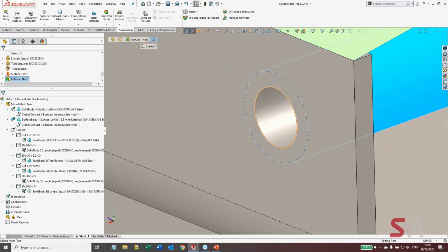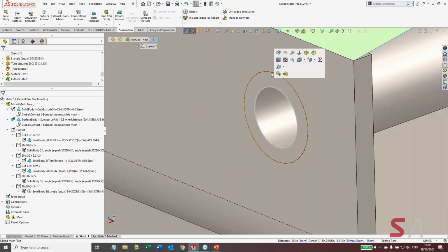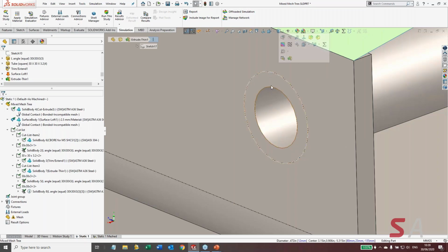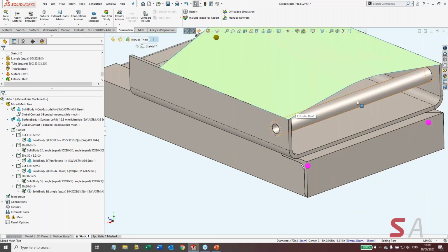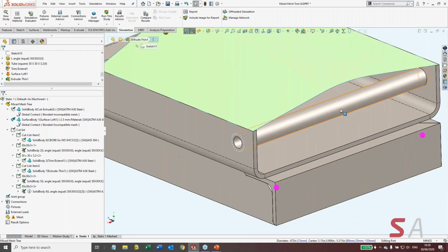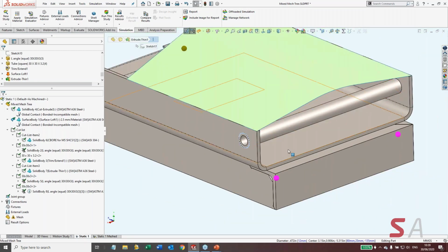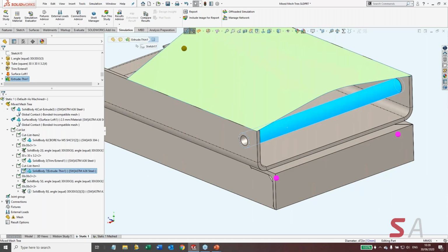So what's my radius here? My outer diameter is 12 millimeters, and my inner diameter is 8 millimeters. So I've got 2 millimeters of thickness. So we're talking about a 1 millimeter mesh all the way through this guy. I don't think so, not really. It's not my favorite thing to do, put a super fine mesh 2 elements thick through that guy.